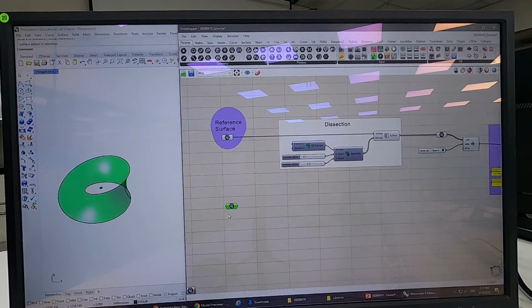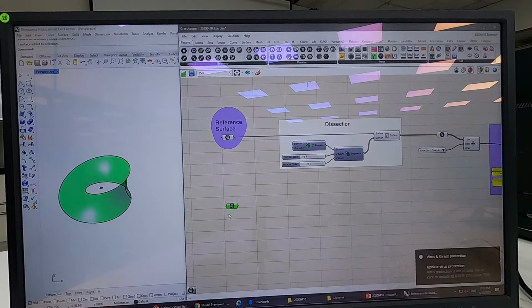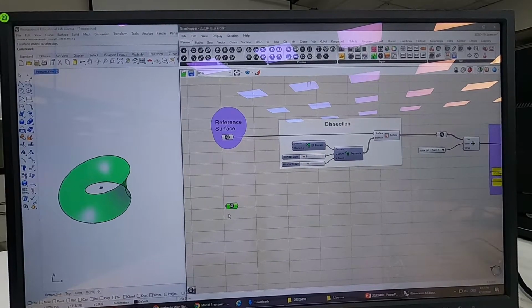Okay. So let's click this surface. It's a container to store surface inside this. And let's click right, and then set one surface. And now you can see here, surface to reference. And you click this one. Okay, yeah. So now you have referenced the Rhino surface to Grasshopper. And should I connect it? I will say that. Okay.